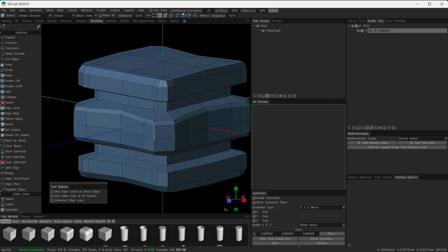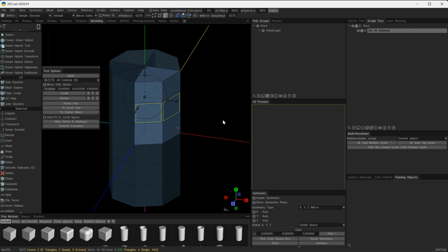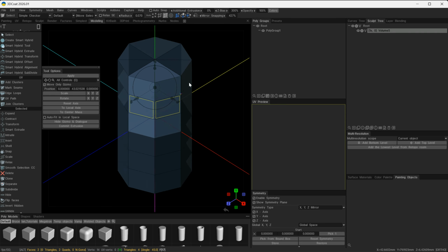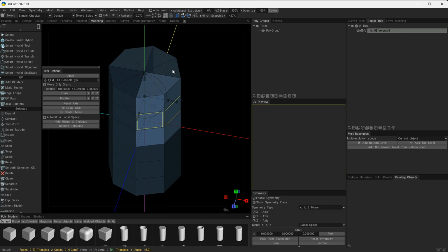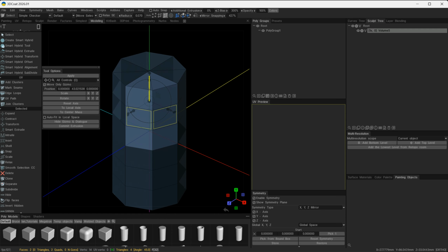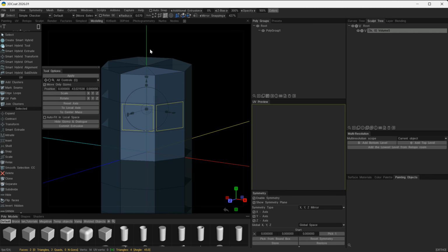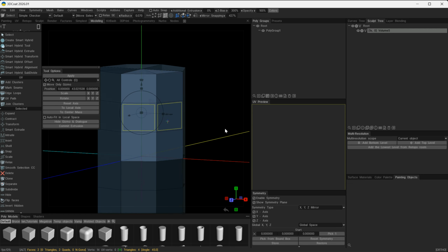Okay, let's look at another shape. So I've got a different shape here. I've got a quarter of a cylinder, and I'm using the mirror to create the rest of my cylinder. So I'm only working with these shaded polygons that you can see here, not the transparent ones. I've selected 2 of the polygons, and I've moved the gizmo to the 0, 0, so it's sitting inside on the Y axis as we did before.